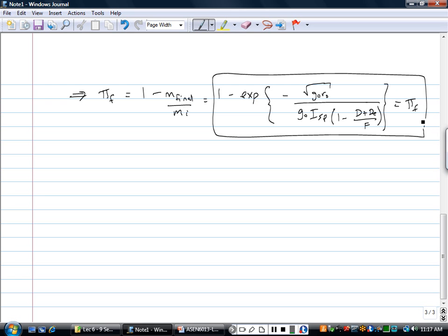So our fuel mass fraction in this case is another somewhat messy looking equation, but we have a thrust to drag term including our installation loss. We have an energy term, which is just our orbital, low Earth orbit energy, and we have a specific impulse for our engine. So it's not really a lot of details to worry about here.